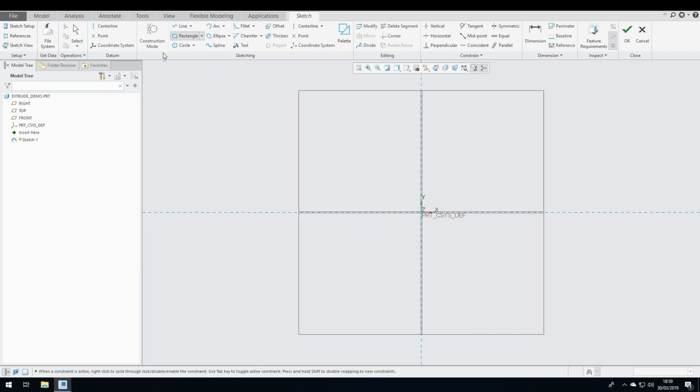So for example, if I do a rectangle, a really simple one, I'll come into the more advanced features of this later. You could then do a construction mode rectangle in there. These lines will be dotted and dashed. This will not affect the extrude that we'll do afterwards. That's just an example of what that would do. So you can do it like that, and if you sketch out and then highlight it, we can delete that because we don't need this.